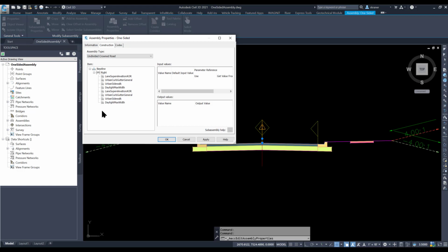This situation can be difficult to recognize because these assemblies appear to be correct in the drawing area. They also can result from minor errors during a common workflow, but this configuration alters the interaction of subassemblies, hindering corridor creation. The resulting errors can be sporadic, making this issue hard to identify, though it's easy to fix.